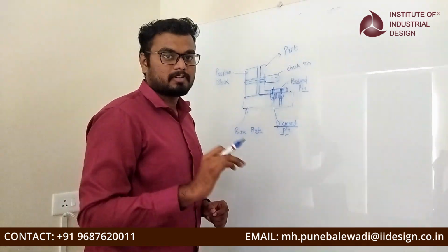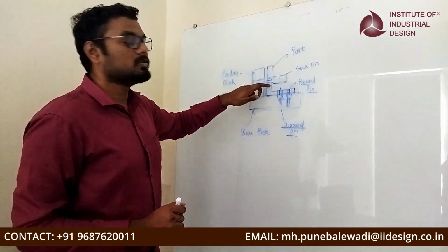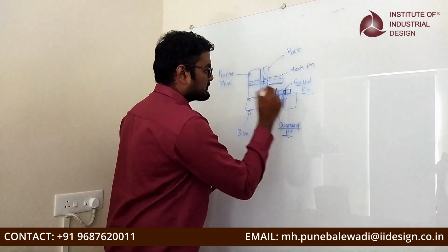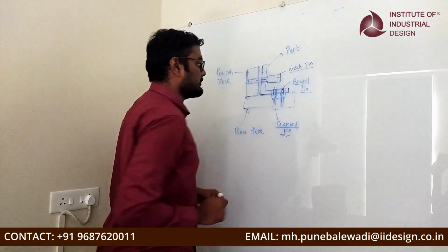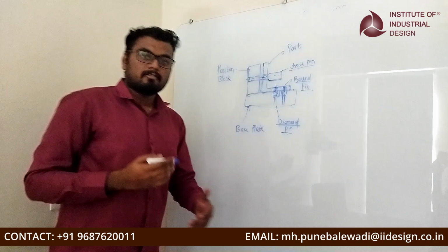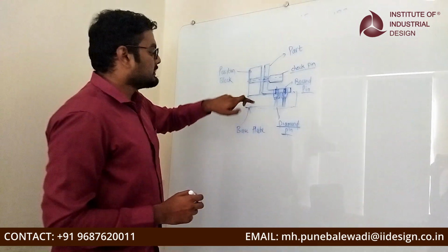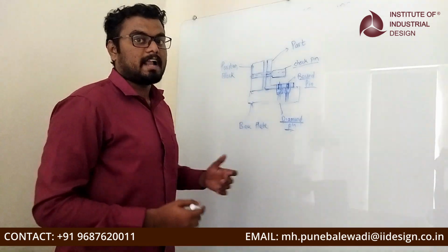Its 6 degrees of freedom are fixed. What was the client's requirement? We had to check this hole's position according to this. So once these two holes are fixed, we are using some calculations, we are designing this check pin. So what will happen? Once the part is manufactured, it will rest on this base plate using the diamond pin and round pin we have designed and manufactured.